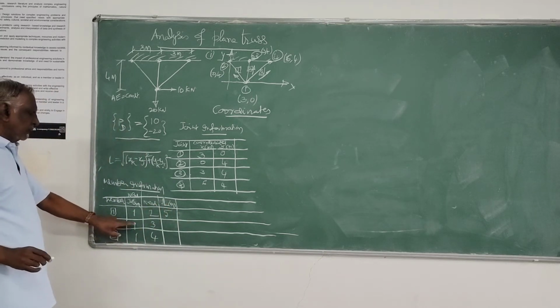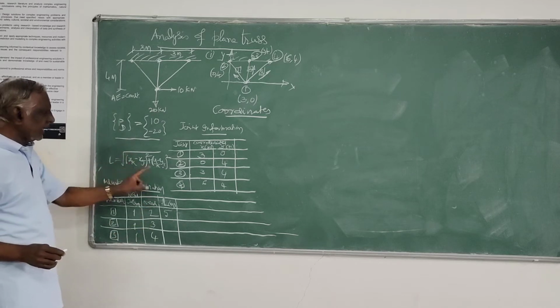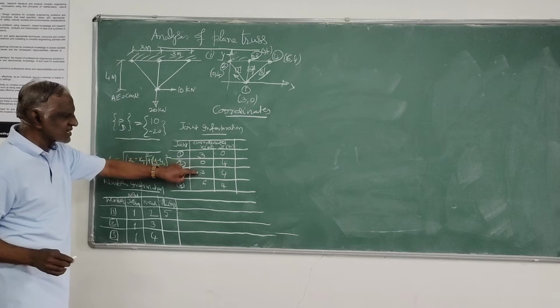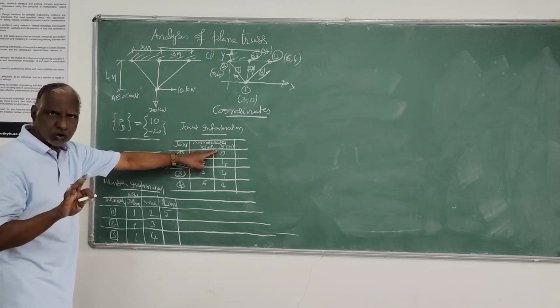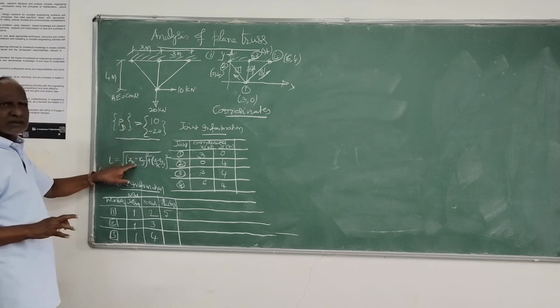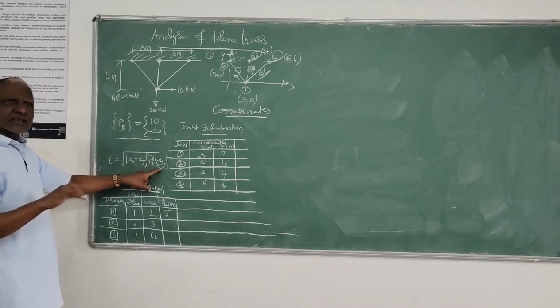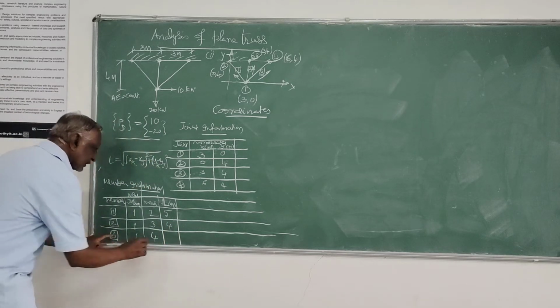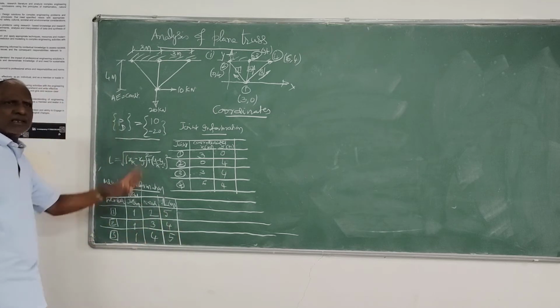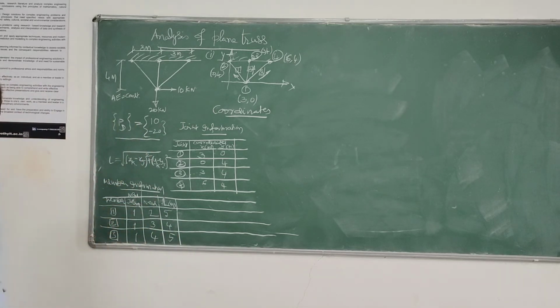Similarly, for member 2, it is 1 and 3, Kn is 3. So xk minus x1 is 3 minus 3, 0, and 4 minus 0 is 4. So the square root of 0 plus 4 squared, that is the square root of 16, that is 4 itself. Similarly for the last one you will get 5. This is how the element property length has been defined.